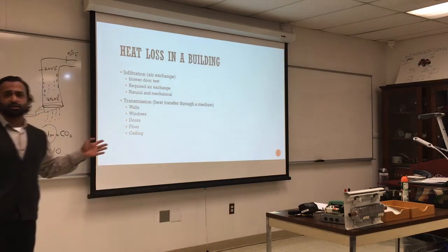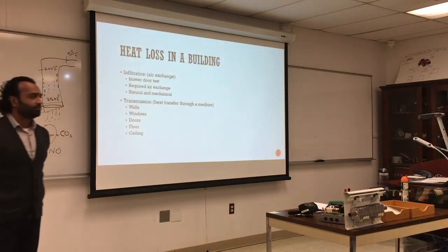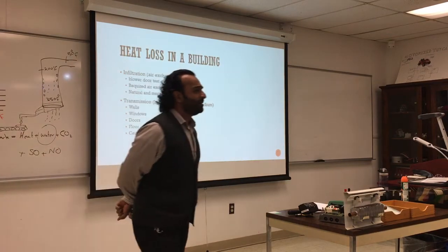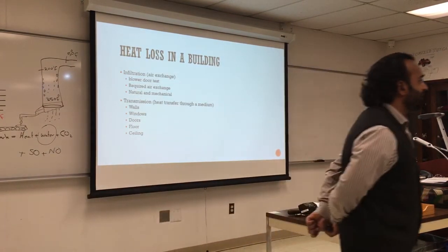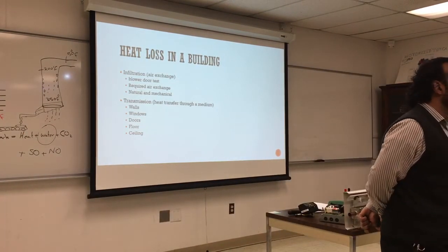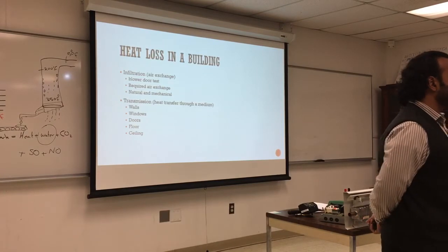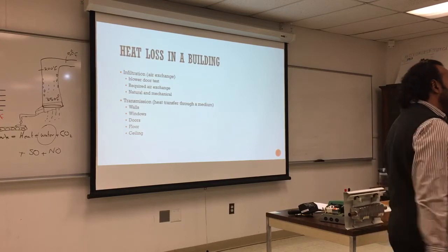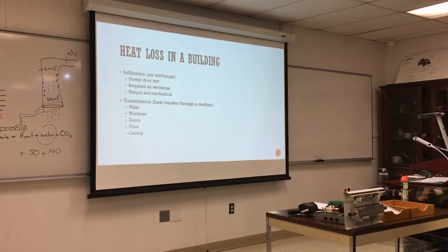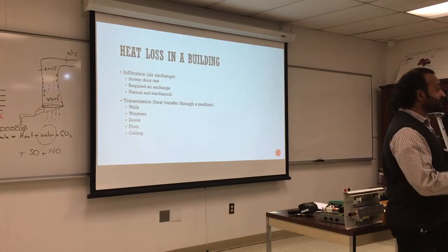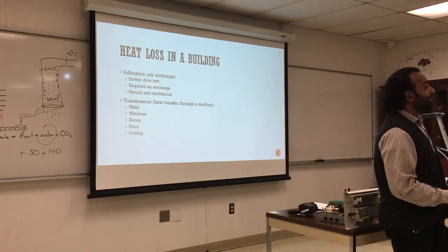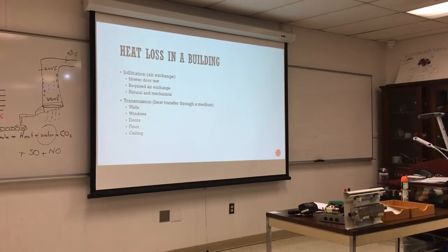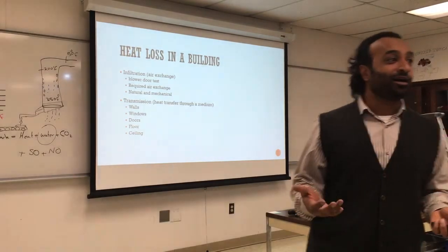Any questions? How much trouble would you be in if you got the wrong BTU? It's not about being in trouble, it's just not going to be a good fit. And it is within your interest and the state's interest to have the proper amount of heat. Otherwise, if you oversize it, it's going to cycle more and it costs you a lot of money. The problem is when you undersize it, you're not going to reach the heat required and people are going to be upset. That's why people always oversize it.